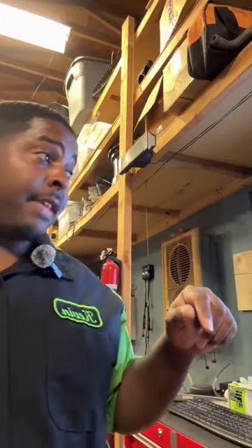But Paul, what I would recommend you do, pull out the center bezel of the truck, slide the radio out, look at the connector on the back side of that radio. It should just be the major one. There may be 2, but you're looking for a black and pink wire.